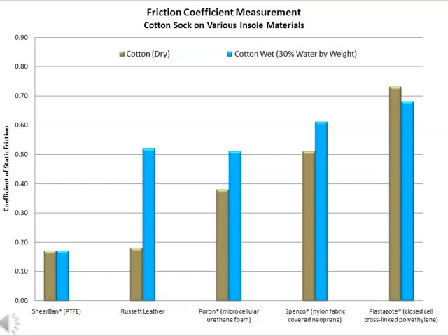A close inspection of Dr. Naylor's data indicates that even a 50% reduction in peak friction will triple the number of cycles necessary to cause open trauma. Ultra-low friction patch material designed for orthotic, prosthetic, pedorthic use is available, consisting of a PTFE film bonded to a thin fabric. Patches of this low-friction composite may be bonded to insoles, orthoses, prostheses, or other containment surfaces in strategic locations bearing against at-risk areas.